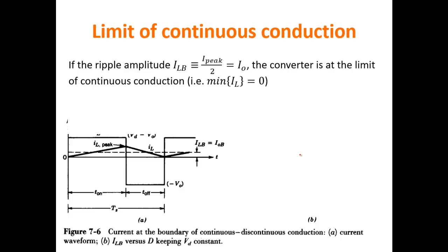When you switch the display off and put the device in standby, the current that is needed goes down by orders of magnitude, by 2 or 3 orders of magnitude depending on the situation. So you're really changing a lot the average current required by the load, and therefore it's very easy to go below this limit.